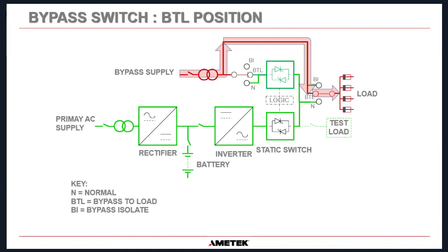Now, I want to caveat this. You have to follow the operations procedure on the front of your UPS to do this. And in truth, you always have to transfer the static switch to bypass before you transfer the manual bypass switch to bypass. I've just got a comment there saying the video has froze, so hopefully that is just one user that the video has frozen for and not everybody else. I have no way to check it, unfortunately, so I'm going to carry on going regardless.